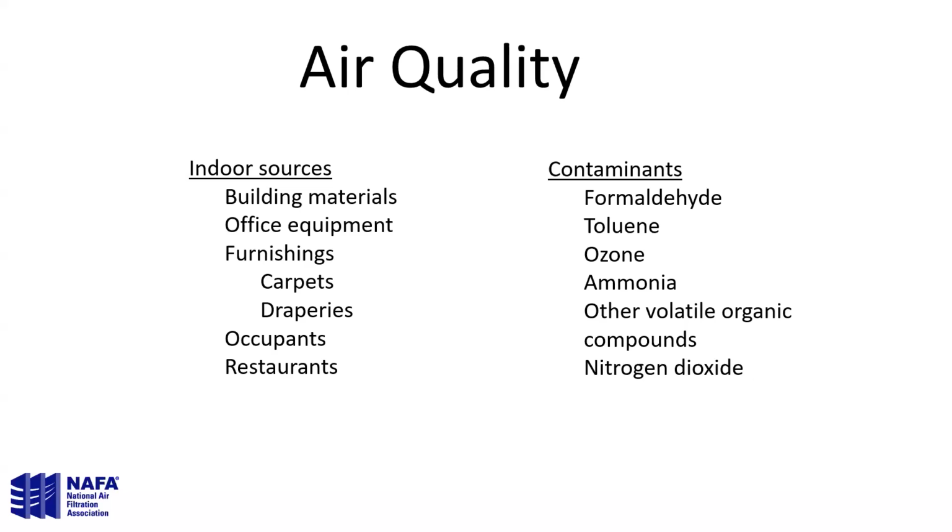Well, this is the fun market, in my opinion, because you don't always know what you're dealing with, but it's also the most difficult one in many cases. In the case of air quality indoor sources, we've got building equipment, we've got office equipment, all of your laser printers and whatnot, they put off ozone. That sweet smell, if you stand there and make a lot of copies, that's actually ozone. You really shouldn't stand there and smell it. In fact, ozone is the only contaminant that's regulated both indoor and outdoor. Furnishings, your carpets, your draperies, all of these things that come new, they might off-gas formaldehyde. They will all off-gas when they're new.